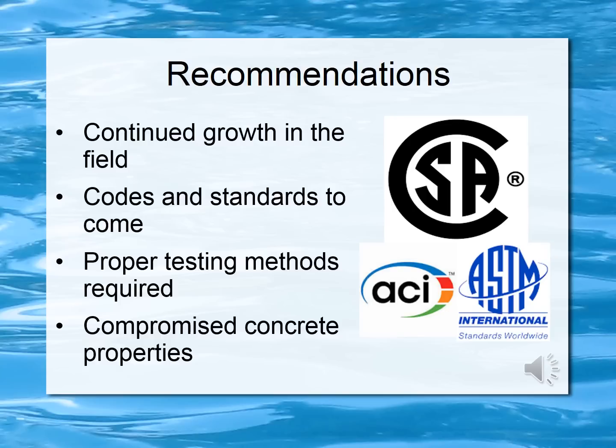What is still needed in the field is a comprehensive set of tests and standards designed specifically for pouring concrete underwater. Currently, standards are in-air tests such as the slump test, and can only give a non-complete understanding of the concrete's characteristics once introduced to the water. The lack of standardized tests and practices increases the risk of substandard mixtures and resulting concrete performance.